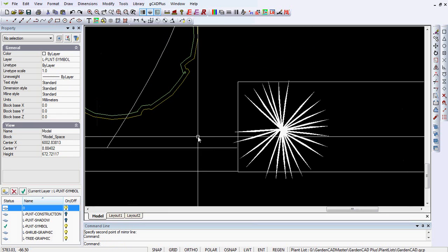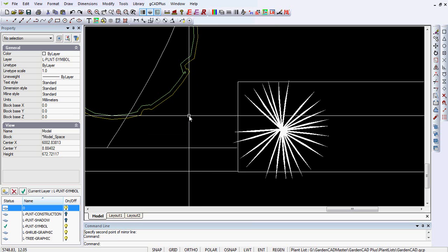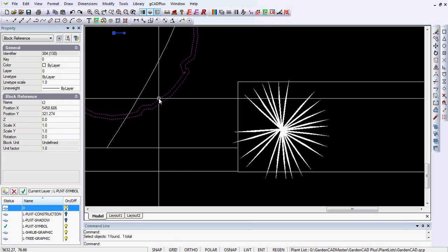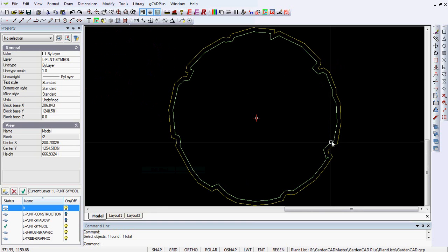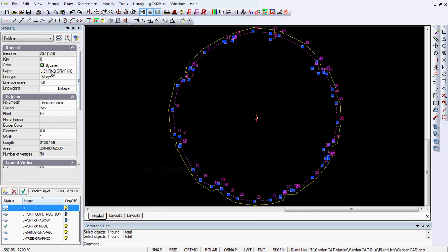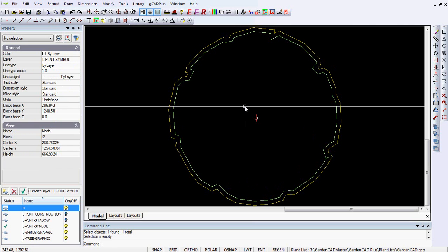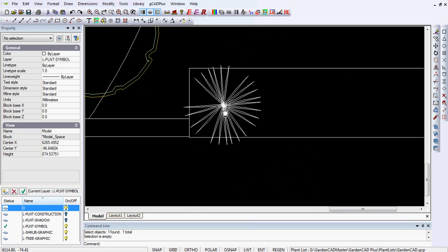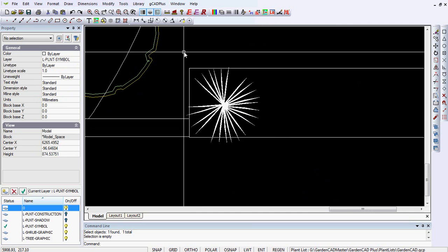If we're going to follow the system that we've used for many of the other symbols, I have a layer here, which is this. If we edit this block here, let's go into edit block. I have an internal layer, which is a symbol on a layer called shrub graphic that's internal. So the next thing, I'll close that block. So what I'd quite like to do is to set a color for all of these entities that we have here now. So let's grab them all.